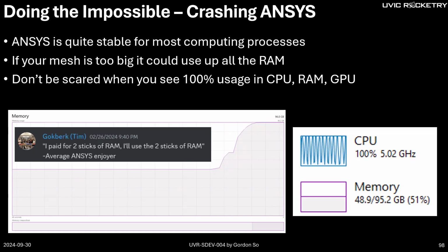So make sure when you do your CFD, you know the limitations of your computer. For example, most laptops can do 2D CFD pretty decently because of the small domain. But anything slightly more complicated, you need a decent computer to run efficiently.